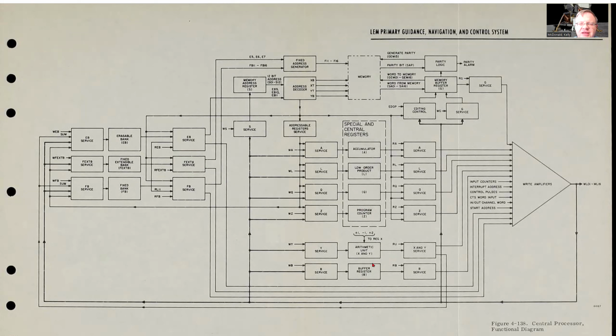These are the main, more general purpose registers. You'll find in the Apollo guidance computer, because they were trying to optimize how the computer performed, each register sometimes has its own little quirks and extra features that they've added to simplify certain mathematical operations like division. So none of them would truly be generic registers. They all have some additional functionality that needs to be implemented along the way.